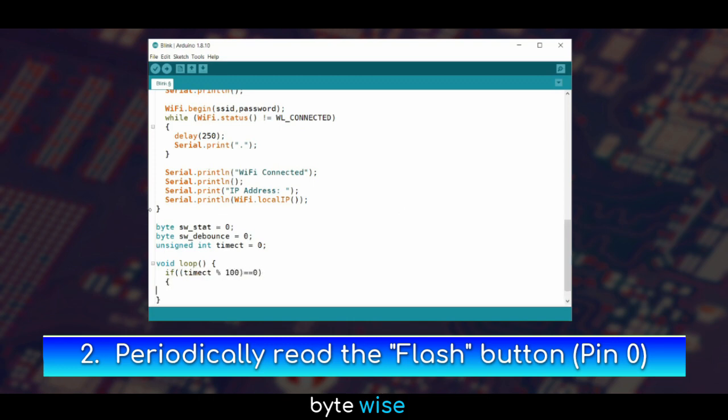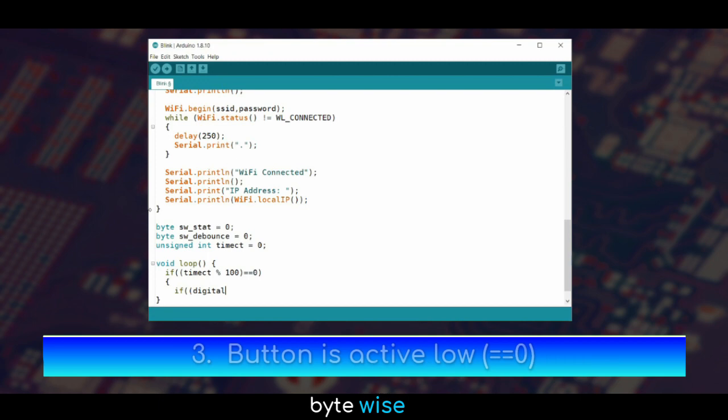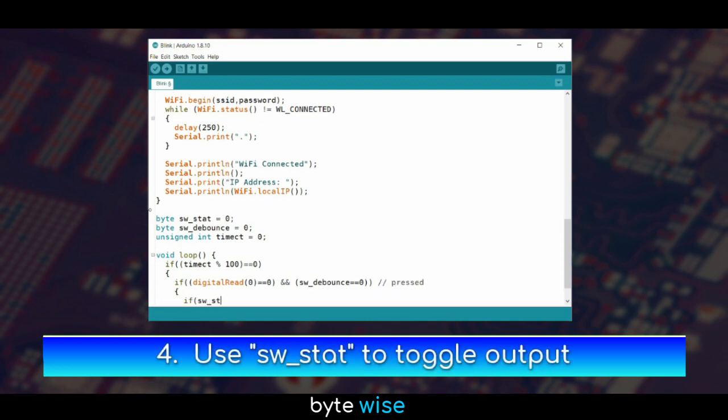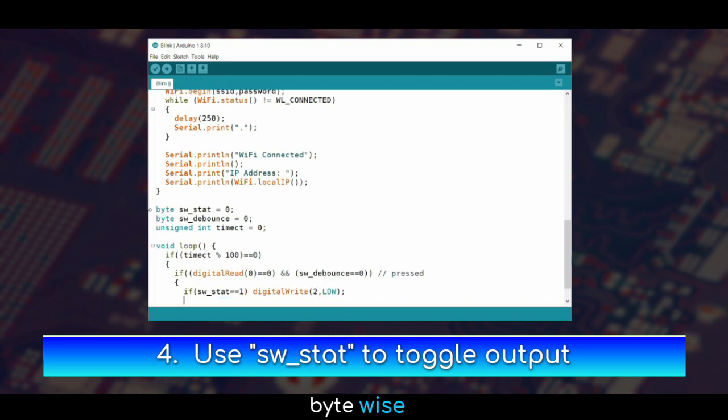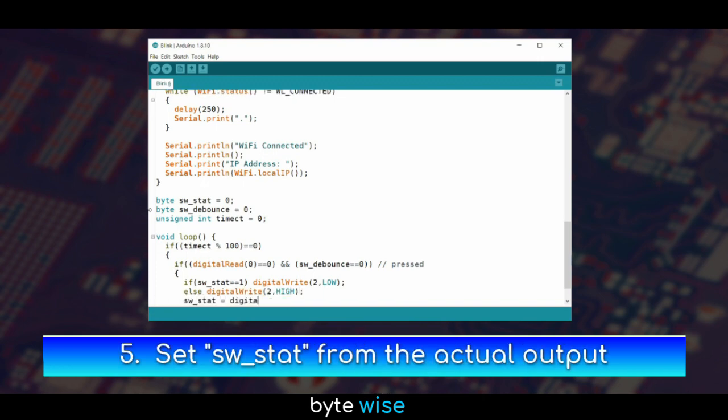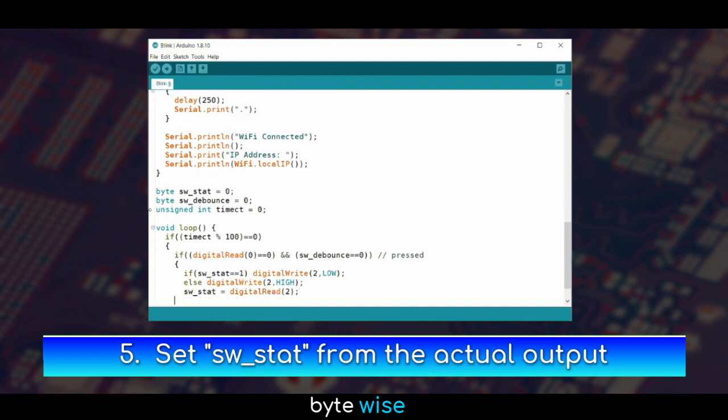The third will turn the loop function into a timing loop. In the Arduino setup, the loop function runs continuously to perform the tasks that the project needs to do. The ESP01 runs at 80 MHz, so the loop function is running extremely frequently and extremely quickly. The program will break that down and only test the GPIO0 pin every 100 loops. The incoming button press will act to toggle the output because there's only 1 button.